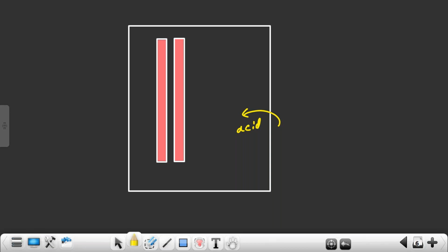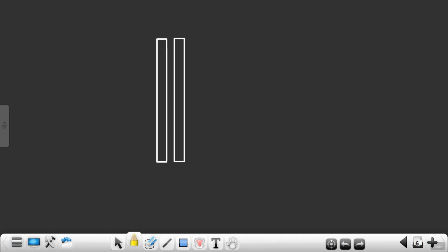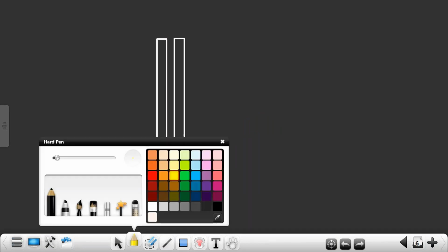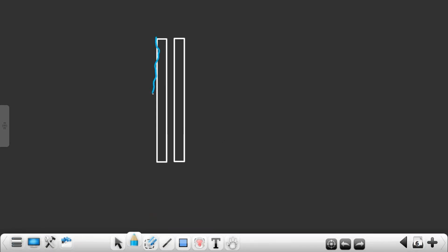So when we have metal layers running parallelly like this, I cannot tell that these metal layers are fabricated properly. See, during acid erosion or acid etching, you can have a metal layer like this. It's not completely planar. I'm telling in nanoscale, remember.